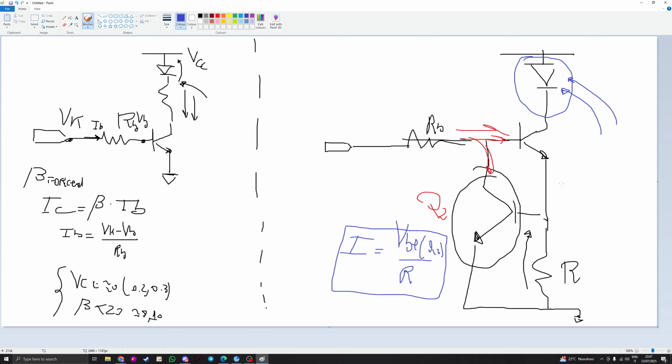This circuit is extremely useful, for instance, when you have to drive optocouplers and you want exactly 1 milliamp or 3 milliamp, something like that. So let's go on LTspice and let's see what happens.